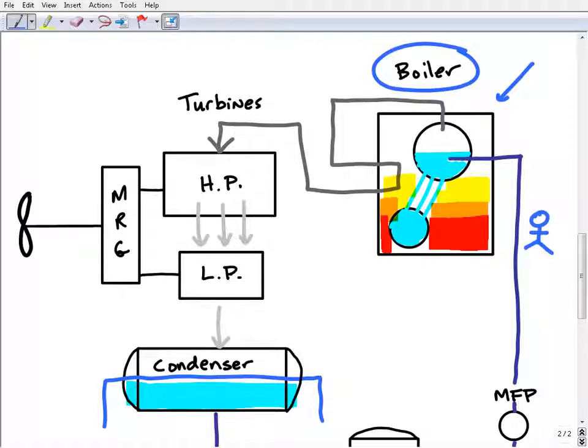But let's get into the boiler here a bit. So you can see here, I'm representing the boiler by two circles. Maritime boilers come in different types, but this is a common type. They basically have water in two drums. This is actually called the water drum down here. And then these lines represent tubes that go up from this big drum.